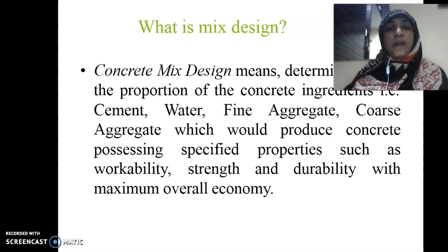In a simple way, what is concrete mix design? To find the proportion of ingredients of concrete which would produce workability, strength, and durability with maximum overall efficiency is called concrete mix design.